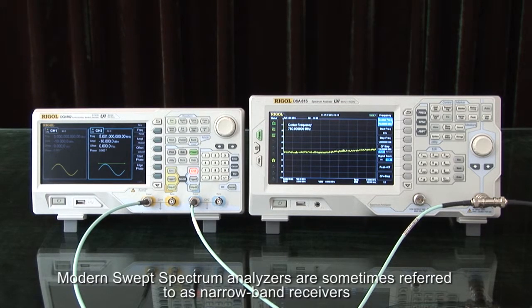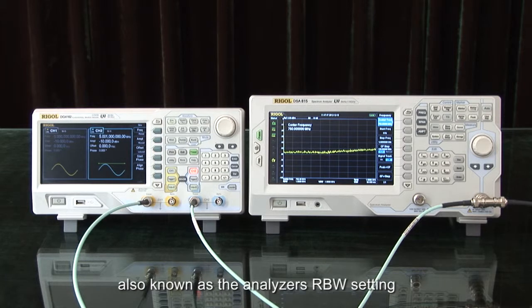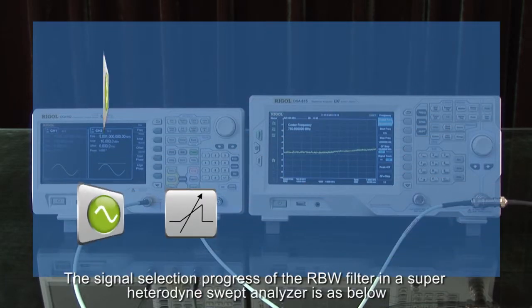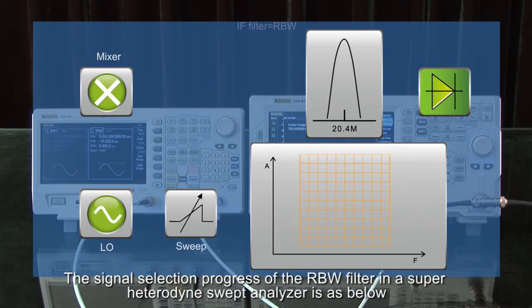Modern swept spectrum analyzers are sometimes referred to as narrowband receivers. This is primarily because they provide an adjustable resolution bandwidth filter, also known as the RBW setting. The signal selection process of the resolution bandwidth filter in a superheterodyne swept analyzer is as below.